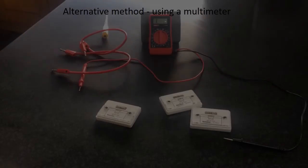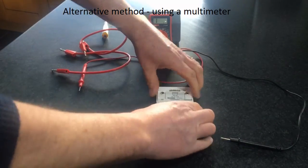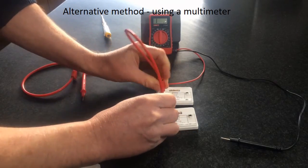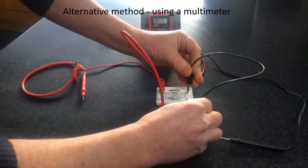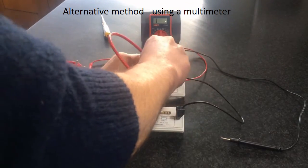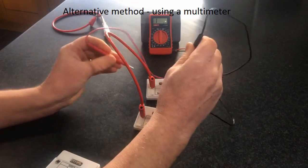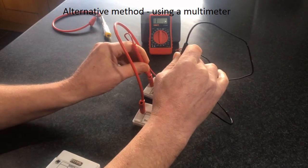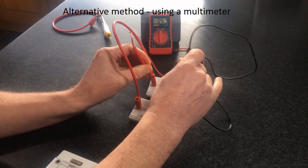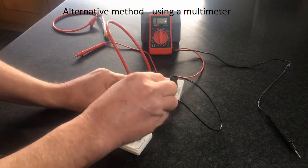And on to putting resistors into parallel. This time I'm going to connect them like that. So that's 2 10 ohm resistors in parallel. And then I'm going to just connect that across there. 5.3 ohms. Let's put a third one in.